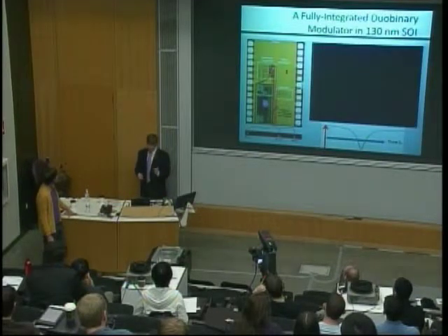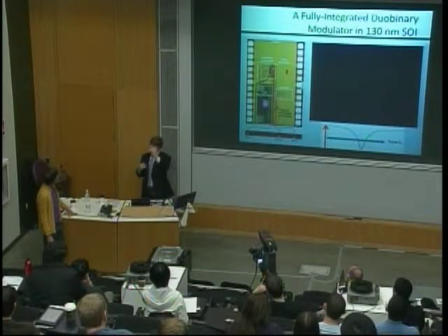And actually, this chip is kind of ugly work. This SOI chip that I showed you earlier was huge. It's 4 millimeters by 0.8. We sent out 5 different versions of it that had small tweaks to the ring modulator. So this is an immense amount of area just to get one working chip. Those small tweaks in the ring are changing the coupling coefficients and basically changing the sharpness of the Lorentzian line shape that I was describing. Using their models and their expertise, we're able to take a ring that we know will work and build the circuits around it.